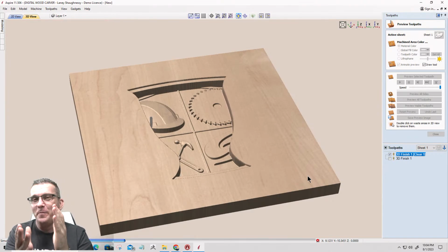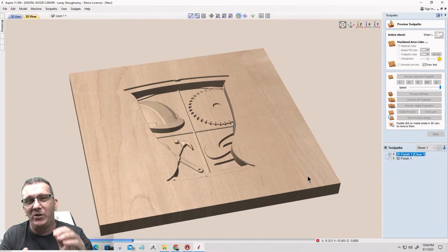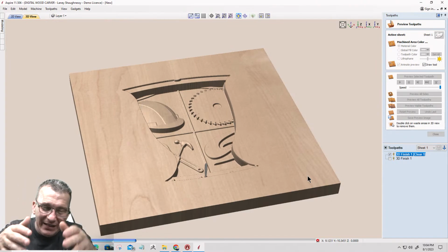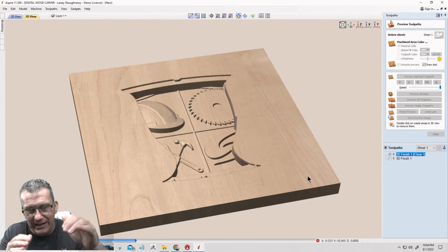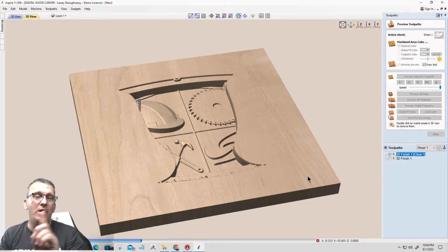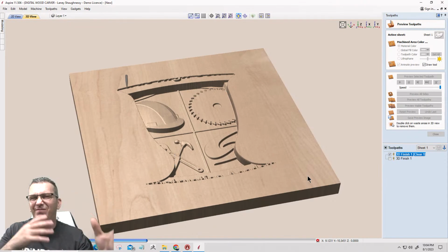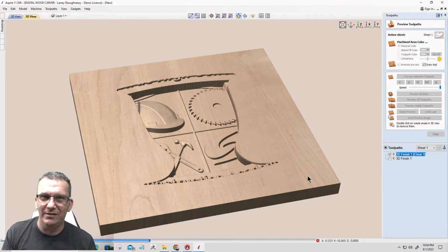All right. With the offset going round and round, I'm going to have some cleanup to do, and I do not want to have to sand in the detail of my 3D model to clean that up. If I'm carving with the grain, I'm going to get a much better carve with less finish sanding required.